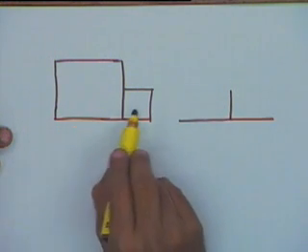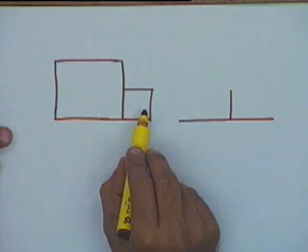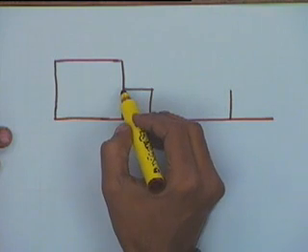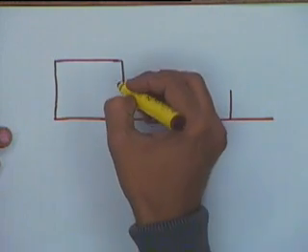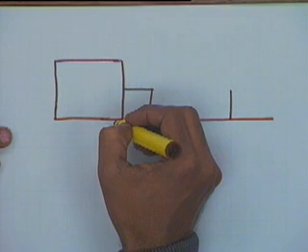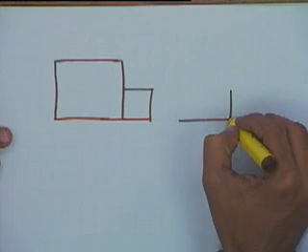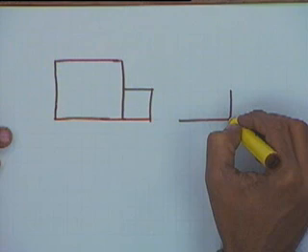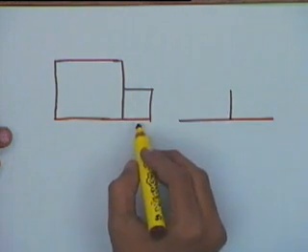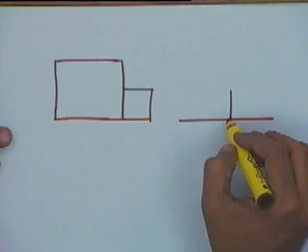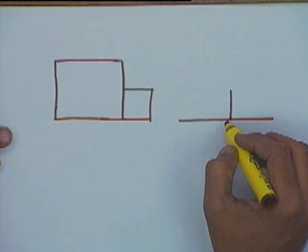Similarly if I want to define a difference of these two, with this set of points minus this set of points, one line will have to be subtracted. So these kind of problems can come up. If I just consider this single line, this is not really the result that one would normally like to have in a solid model. If we have a cube and another cube kept side by side, I will ideally like to say that the intersection is a null set.